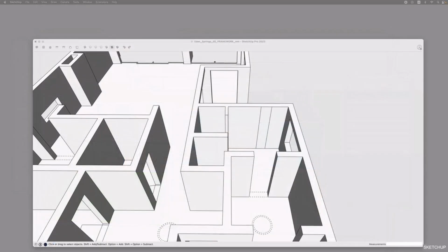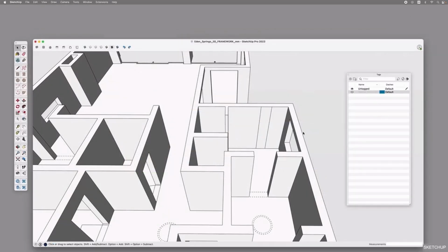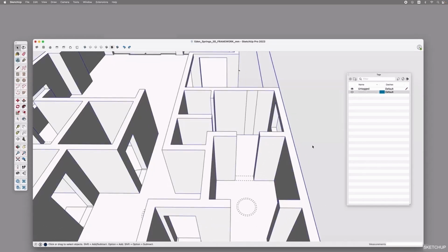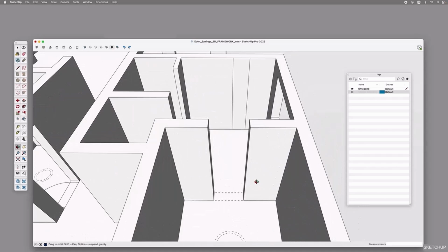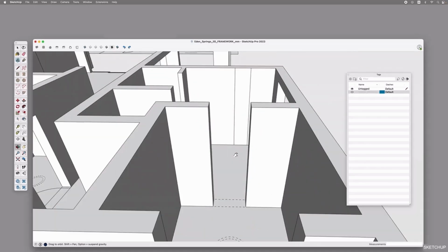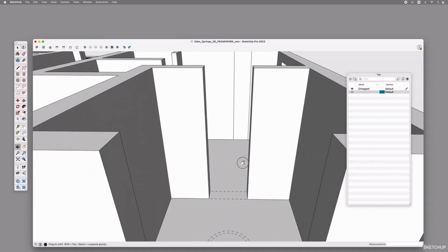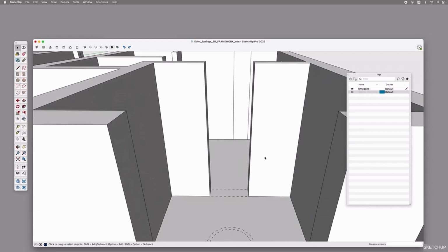Now, let's move on to creating the arched openings based on our Eden Springs floor plan. I prefer starting outside the wall group to maintain flexibility and moving the arch. As you know, within my group, everything will stick together. We have previously set the openings for the doors at a height of 2200 millimeters or 86.61 inches. Let's create a guide for this.